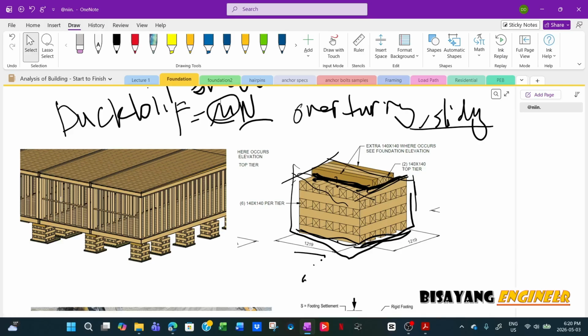Then they move the unit and we check it, because all you have to do, since this is relocatable, is check the snow load, wind load, and seismic load at the final location. If you move this to another location, you have to make sure the building is still okay for snow load, wind load, and seismic load, and then you design the new cribbing.